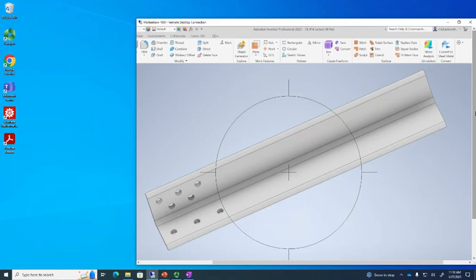Okay? But another potential failure path, because remember, these are the lead line of bolts right here, is a path that looks like this. We go down, over, down, right? And so that path is going to be the gross area minus how many bolts? 3. But then we're going to have to add how many stagger factors? 2. The problem with one of those stagger factors is that here's 1, right?